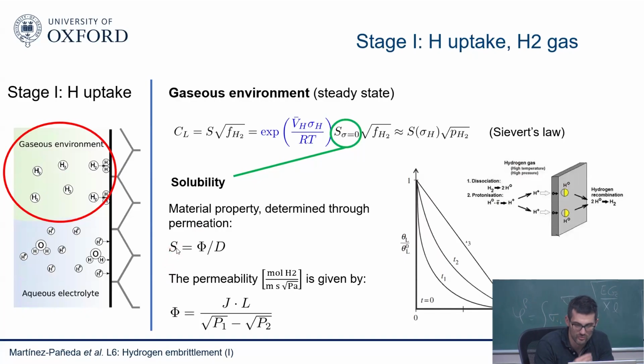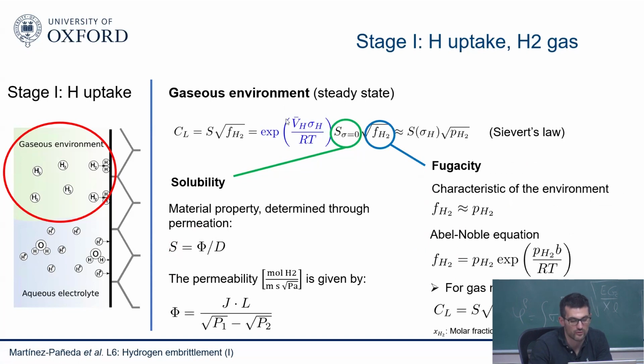But that's the point I wanted to make. And then the other aspect: you have three ingredients. The first one comes from a finite element simulation. You know the stress-strain behavior of your material: Young's modulus, Poisson ratio, yield stress, strain hardening exponent. You run a finite element and you get the hydrostatic stress.